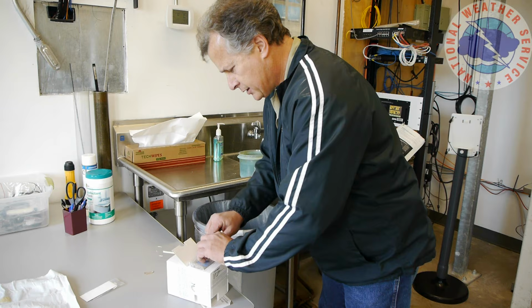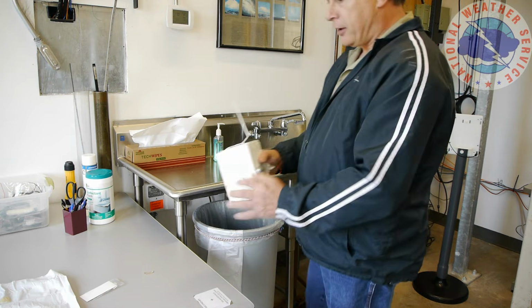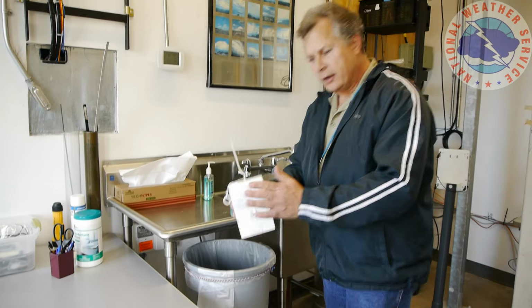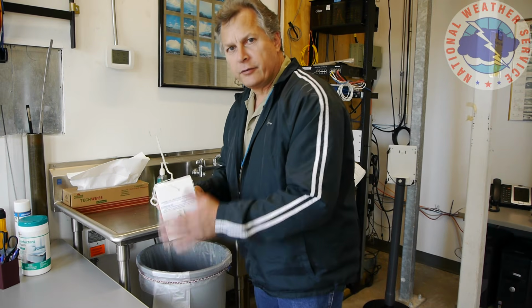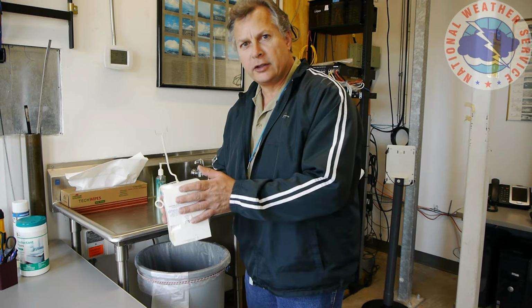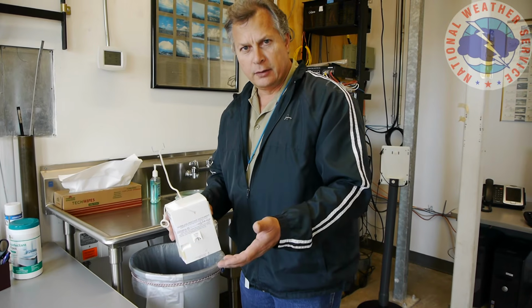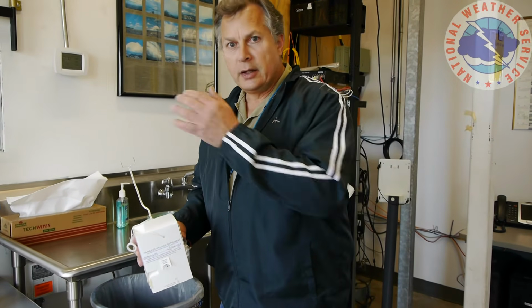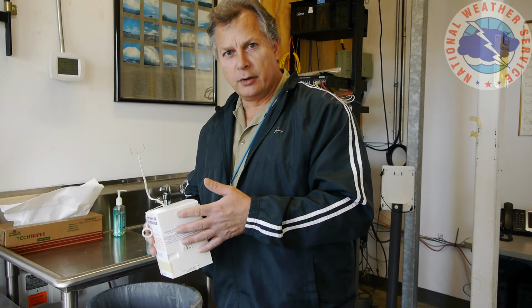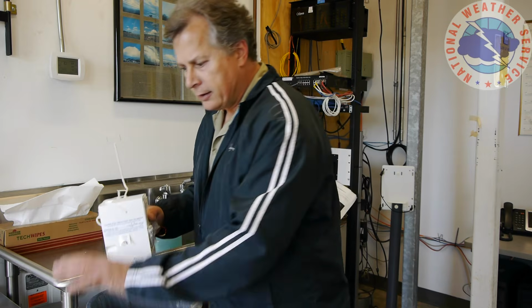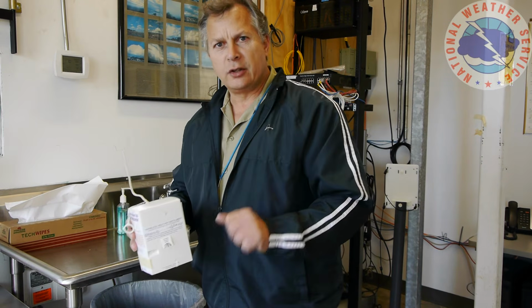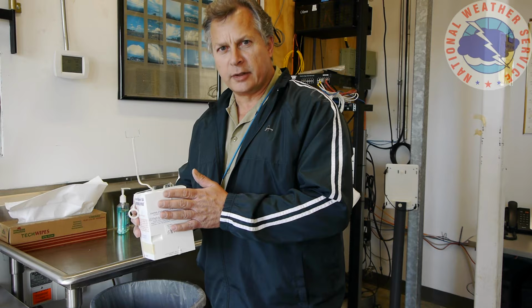Now once I get this connected, I immediately lift this up off the solid surface. If I were to leave this on the solid surface like this table, some of the radio energy from the transmitter would be reflected back into the instrument and would damage it. Later, when we go in the inflation room to attach this to the balloon, I'll put it on the block of styrofoam, which has the same effect. It dampens the reflection of the radio energy back into the instrument.